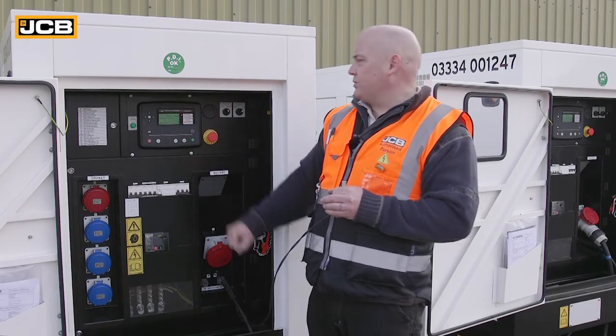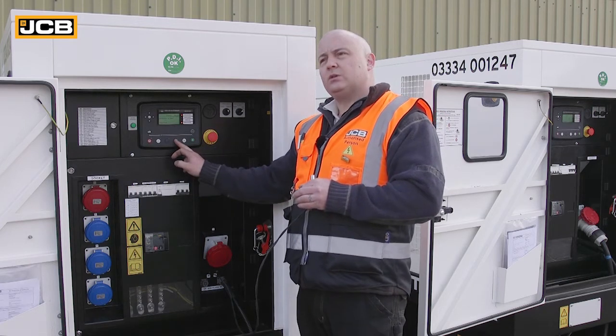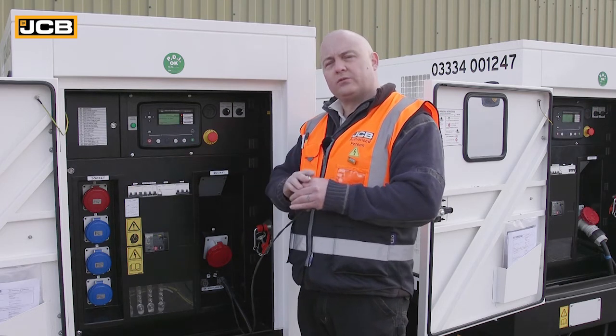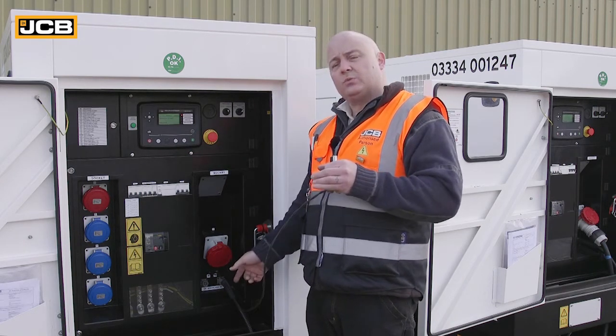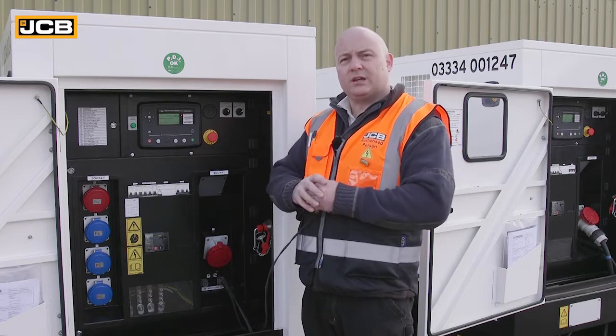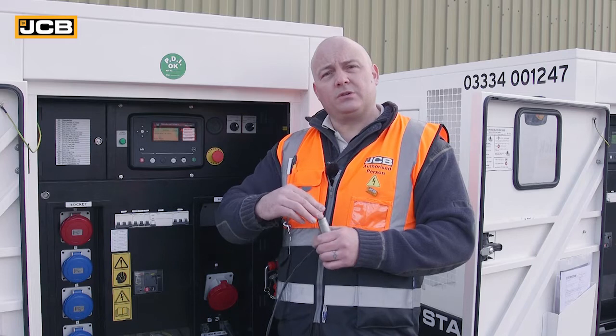Then on the DeepSea control panel, we'll clear any alarms and set the control panel into auto mode, and then it will look for the signal from this switch to start all of the generators in the set. We only need the switch going into one unit, and they will all communicate on the CAN bus network, so they all see that remote start switch. So now I'll close the connection on that switch.